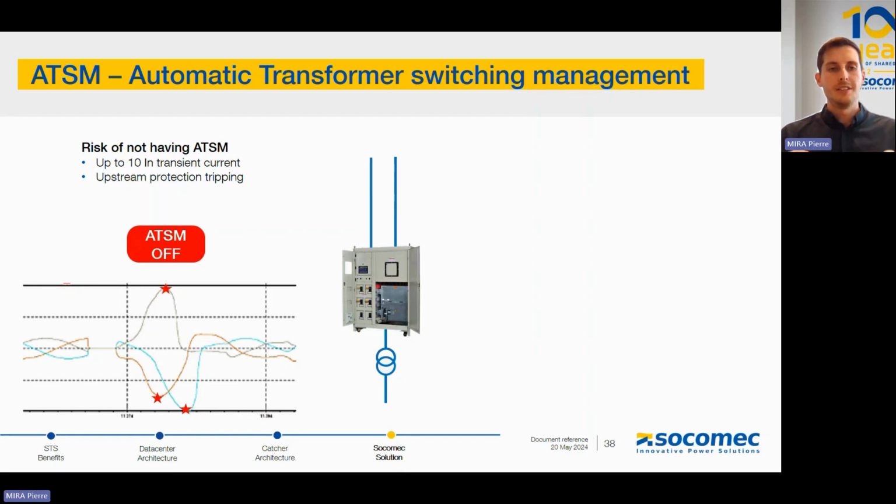We are in North America working with PDUs. STS are connected upstream of PDUs. So it will initiate transfer on transformers being in the PDUs. When there is no specific algorithm, and when we do the transfer in 5 milliseconds on a PDU with a transformer, it will create an inrush. It's something that we don't want, and it's created by the transformer because a transformer has some magnetic flux, creating some inrush currents when there is a transfer very fast.